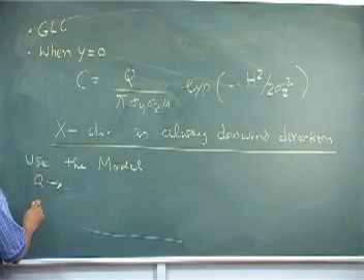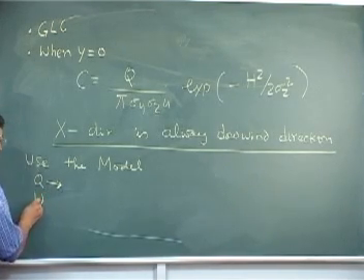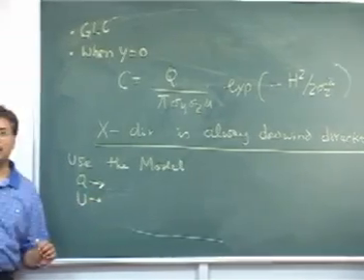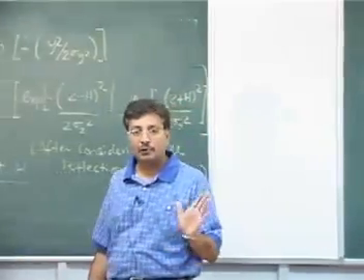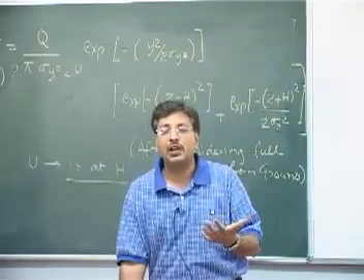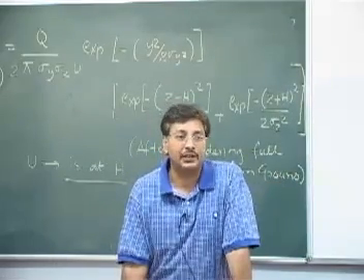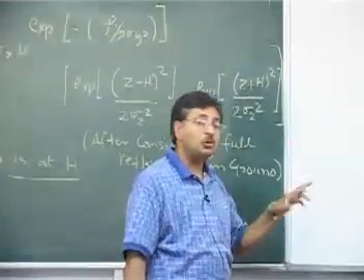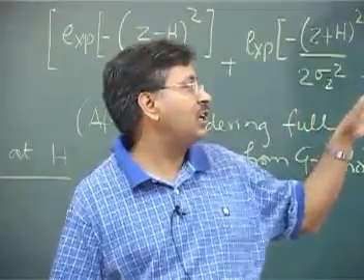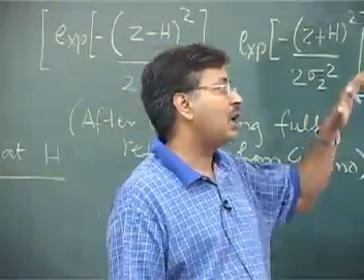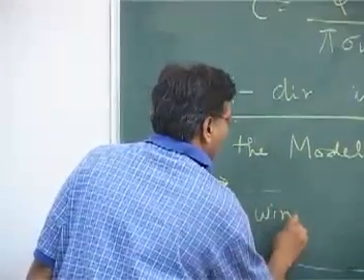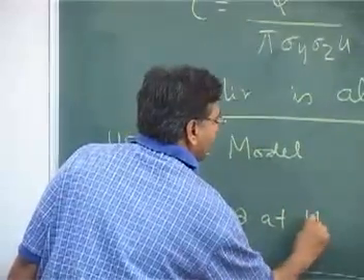The other thing which you need to know is U. How can you get this U? You cannot get this U so easily, but you get the U from the ground level measurements. If not, you can at least go to the airport and find out what is the U in that area. But what they will give you is the surface wind. No one will be able to give you very easily what the wind will be at the stack height. So this one we need to answer, but we'll answer it a little later.